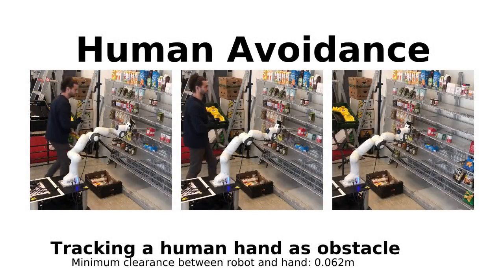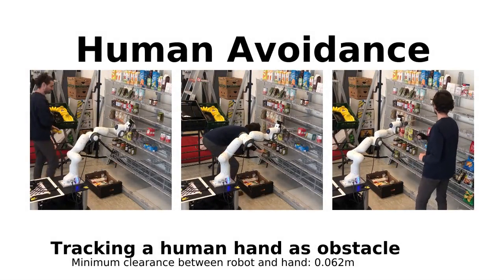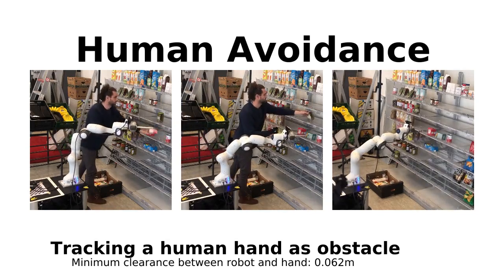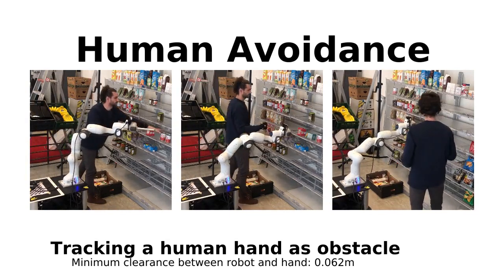We show that dynamic fabrics can be applied to human-robot cooperation scenarios. In this experiment, the hand of the human is tracked by a motion capture system and fed into the dynamic fabric motion generator using a constant velocity model. We can clearly see that the robot is smoothly avoiding the human while converging back to the goal post once the space is freed again.